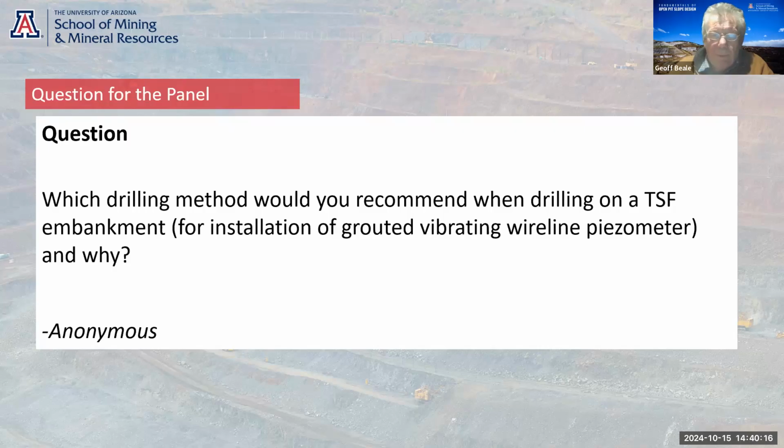Probably, I'll take a crack if nobody else will. Probably Sonic. I think there's a lot of discussion with some of the recent TSF instabilities about using any kind of fluid for drilling, not so much in the embankments, I guess, but in the tailings itself. But if you're drilling TSF embankments, it depends on what the embankment is, whether it's a sand dam or a rockfill dam. If it's a rockfill dam, probably Sonic.